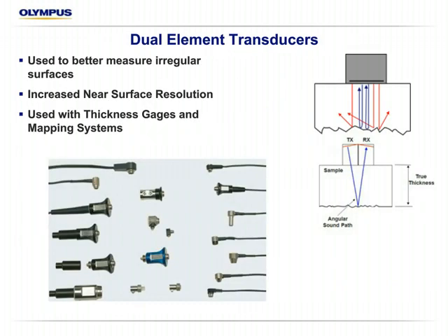The reason we tend to use those in a corrosion survey, especially for general wall loss and pitted back walls, is if we just use a conventional ultrasonic 0-degree transducer, we send sound into the part at 0, and because of this irregular surface, it'll often be misdirected, and the transducer will never see the response.